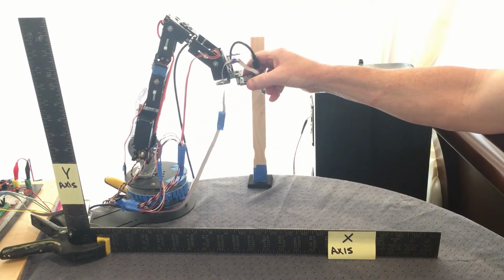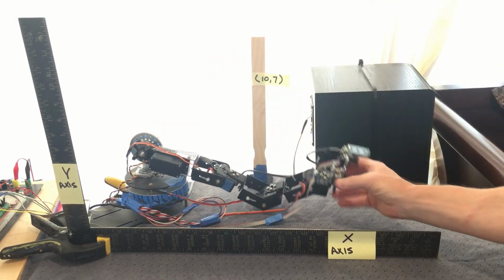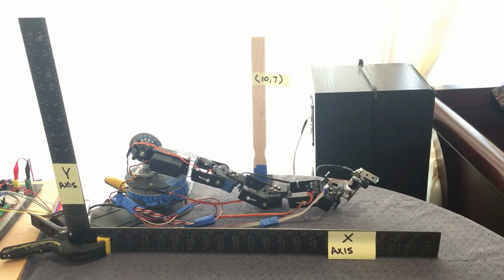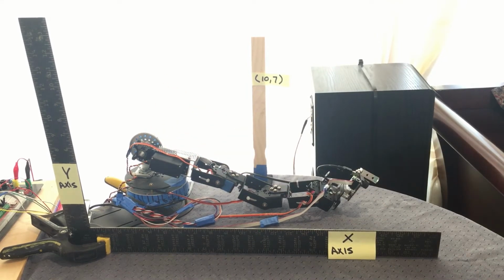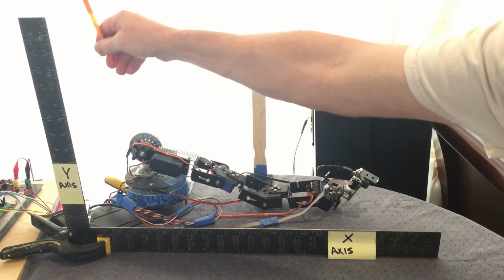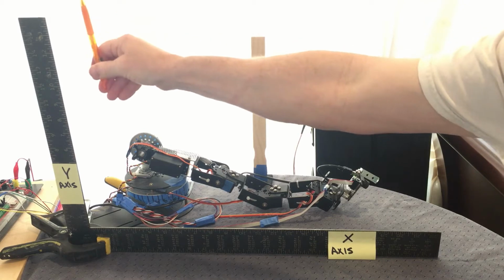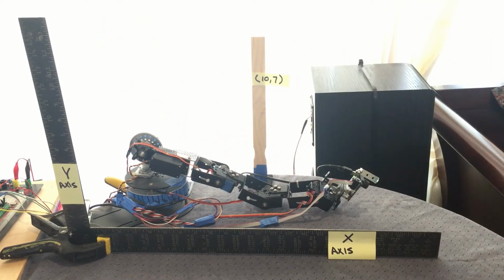So I'm reaching over like this, not reaching under like that. In addition, I have some other limitations. This gearbox servo here only goes from 30, or else it bottoms out, up to 65, which is vertical, not 90. So in my code, I have to account for this a little bit.